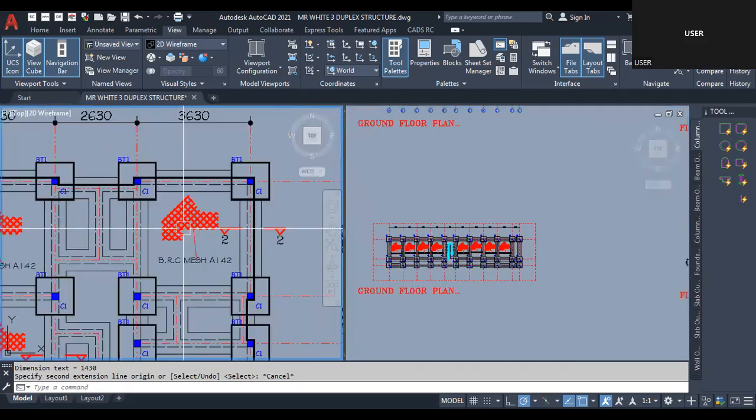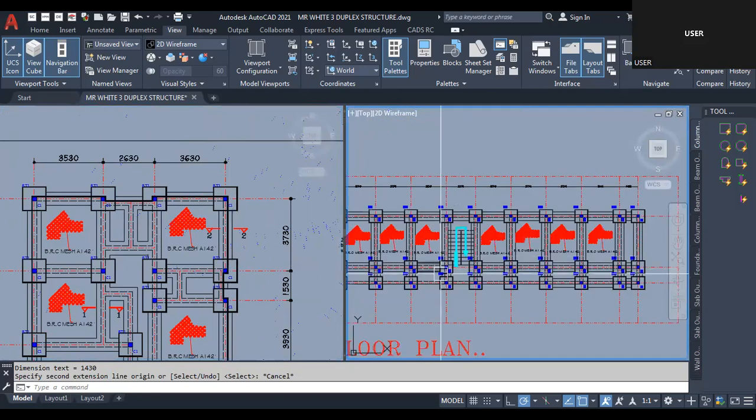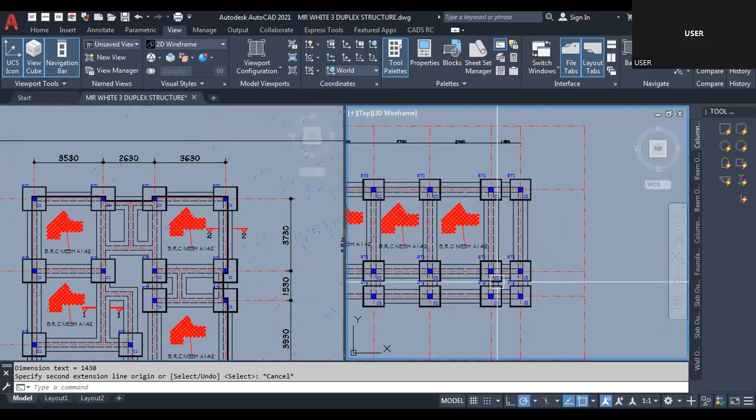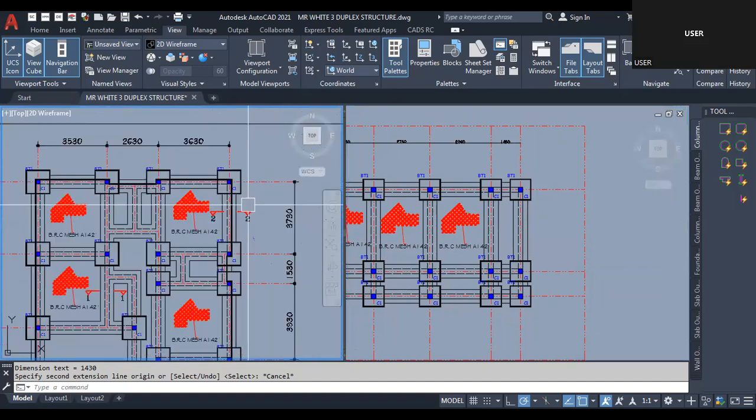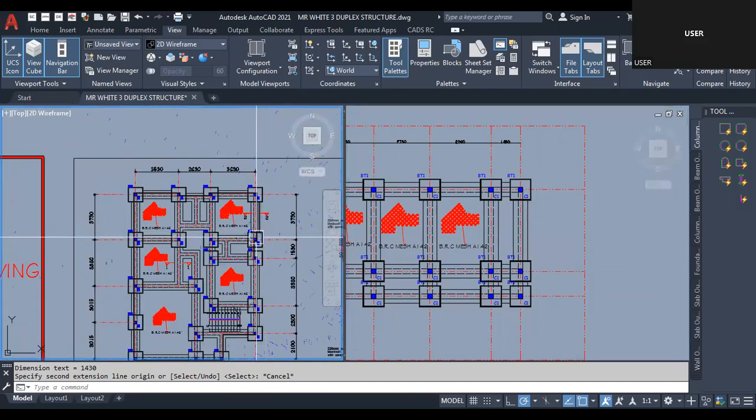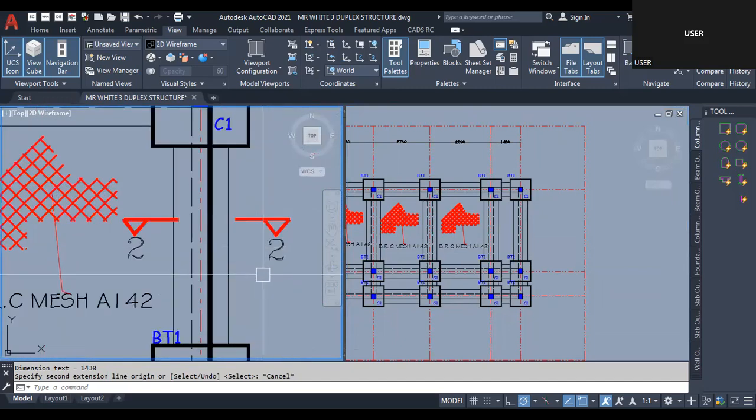Okay, having done that, you have to take a cross section to show the depth of that foundation and then the width of that strip. Okay, so you specify the width of your trench, the depth of the foundation. Cross section 2 will give us an L shape.